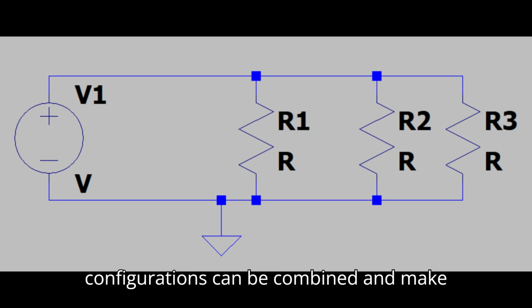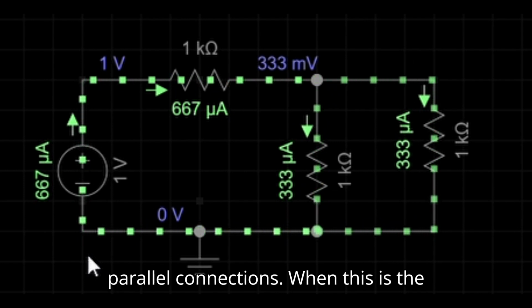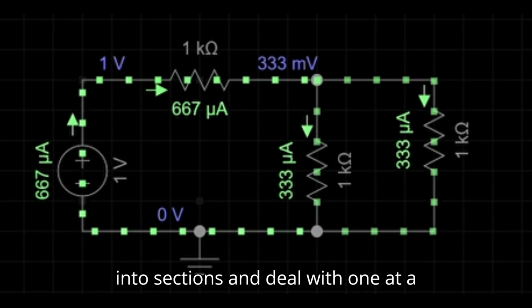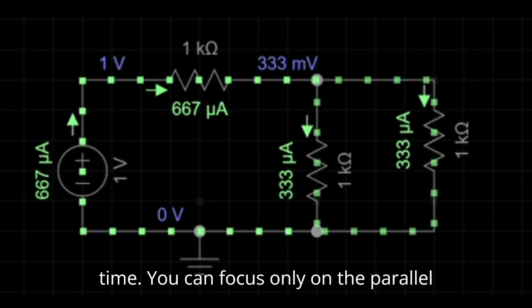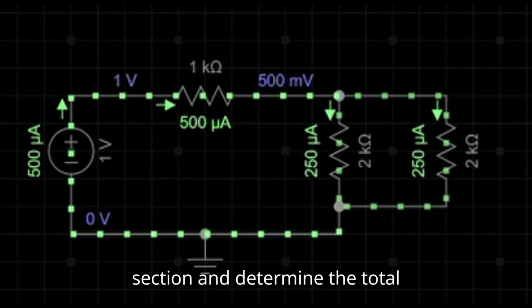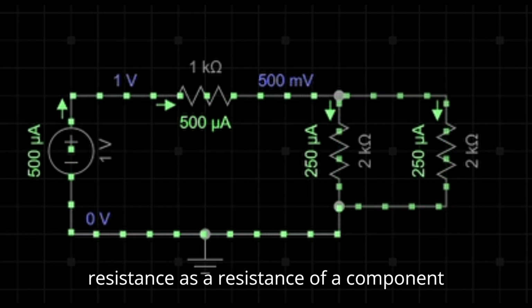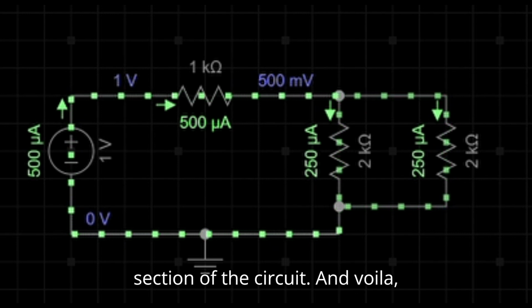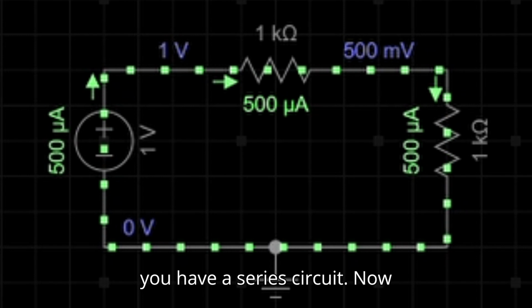These two configurations can be combined and make up a circuit that has both series and parallel connections. When this is the case, you simply break down the circuit into sections and deal with one at a time. You can focus only on the parallel section and determine the total resistance of it, and then use that total resistance as the resistance of a component that is now in series with the series section of the circuit. And voila! You have a series circuit.